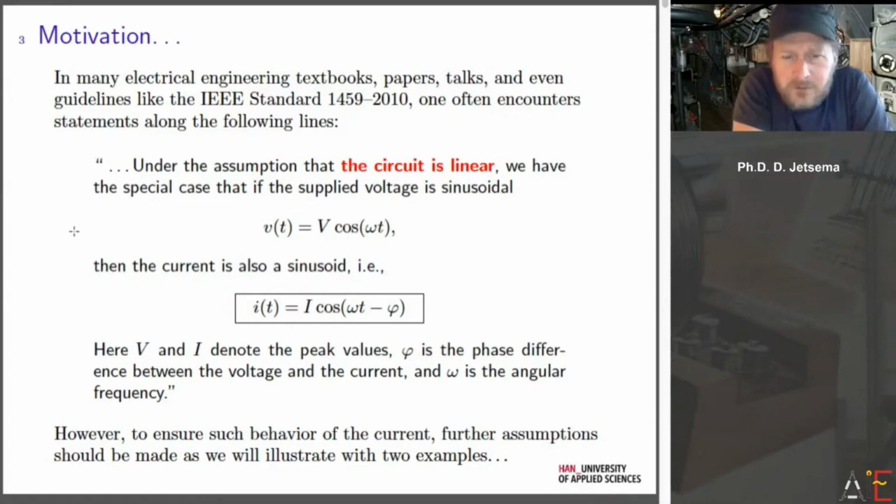And that is that, under the assumption that a load, or just an electrical circuit in general, is linear, when you excite it with a purely sinusoidal voltage, then because of linearity it is assumed that the current will also be a pure sinusoid, of course with a different amplitude than the voltage in general, and perhaps a phase shift.